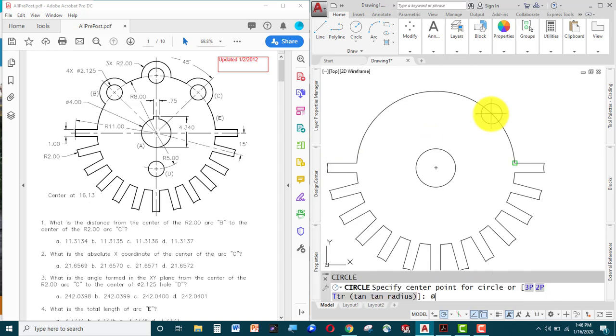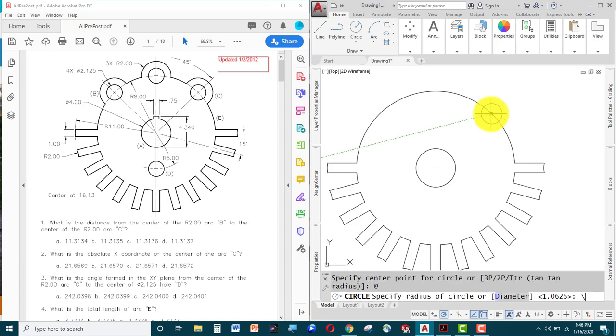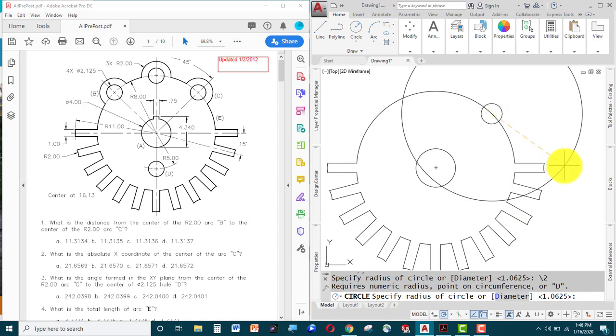Enter gives me the circle command back. It just repeats my last command. The @ symbol selects the last point that I entered. If I type 2 now, it'll draw an arc with a radius of 2.